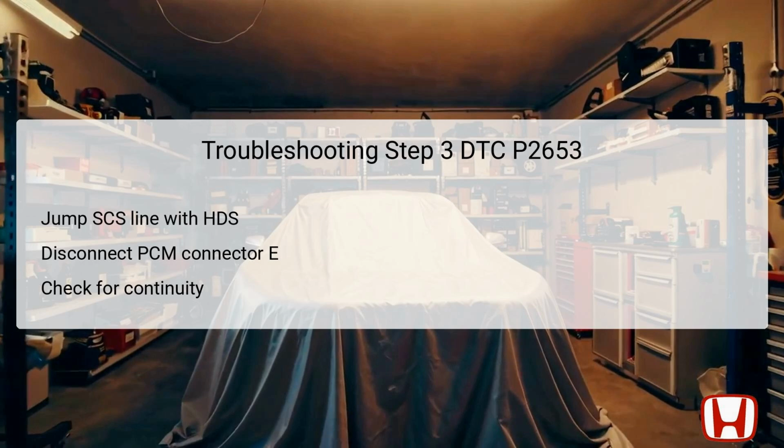The technician should then check for continuity between specific test points, namely from PCM connector E pin 65 to the body ground. Establishing continuity confirms that there is no short circuit in the VTS2 wiring between the PCM and the rocker arm oil control solenoid. If continuity is present, it suggests that a short is affecting the wire, necessitating repairs. If continuity is not found, it indicates that the VTS2 wire is functioning properly, prompting a review for potential service bulletins or even substitution with a known good PCM.